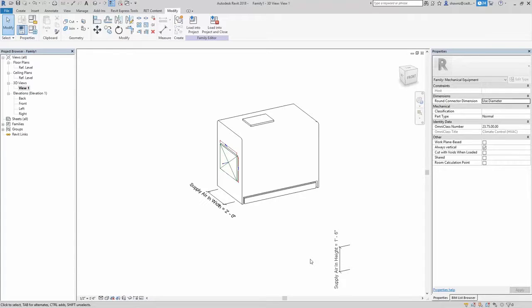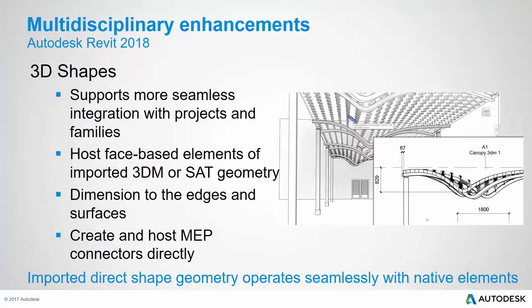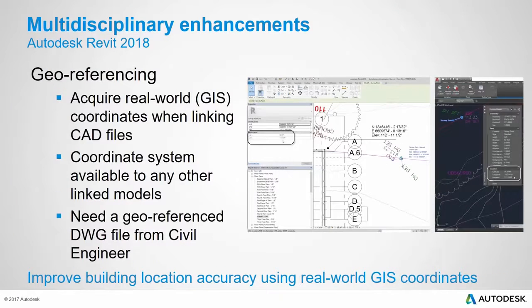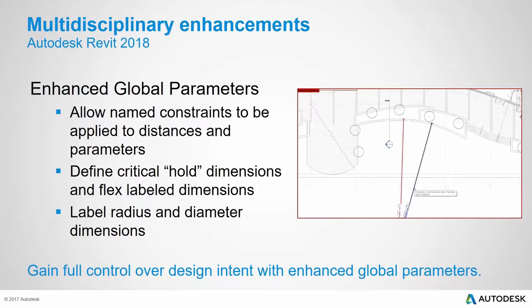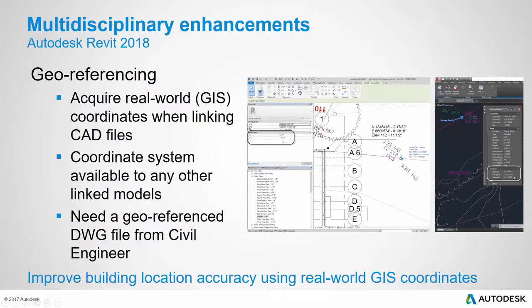So if you do insert an AutoCAD file origin to origin, this is, again, taking a step back here to that DWG site. Let me go back to my PowerPoint here. That pop up on screen. So this georeferencing here, sorry, I didn't see that question a little earlier. This georeferencing, when you do link this in, you do have to be within the 25-mile radius. If you do origin to origin and it exceeds that, Revit will automatically center that DWG on screen.